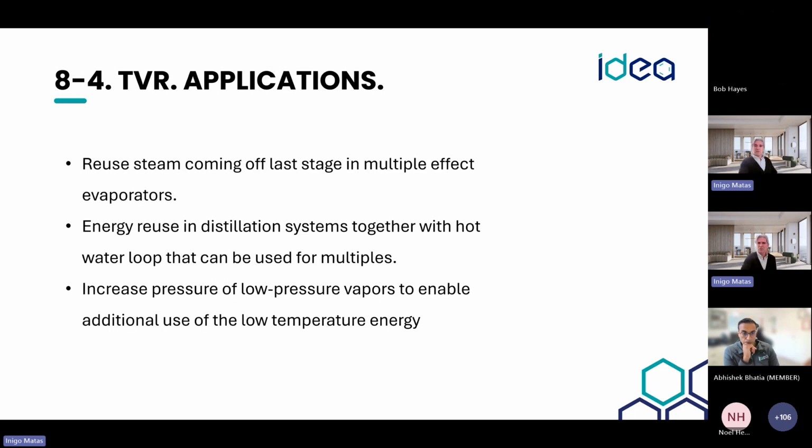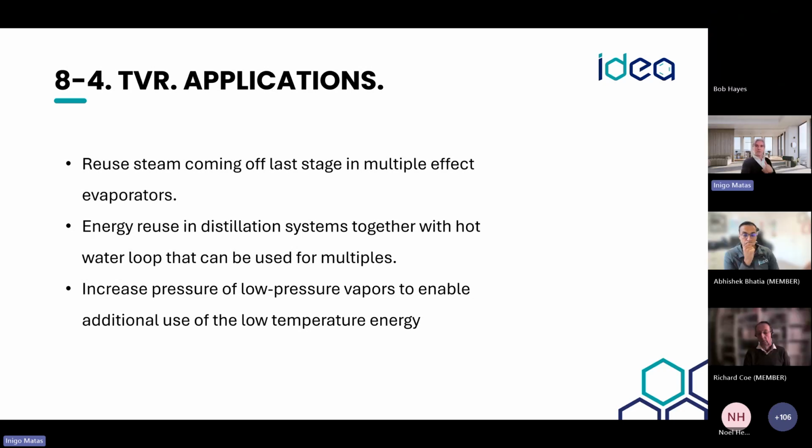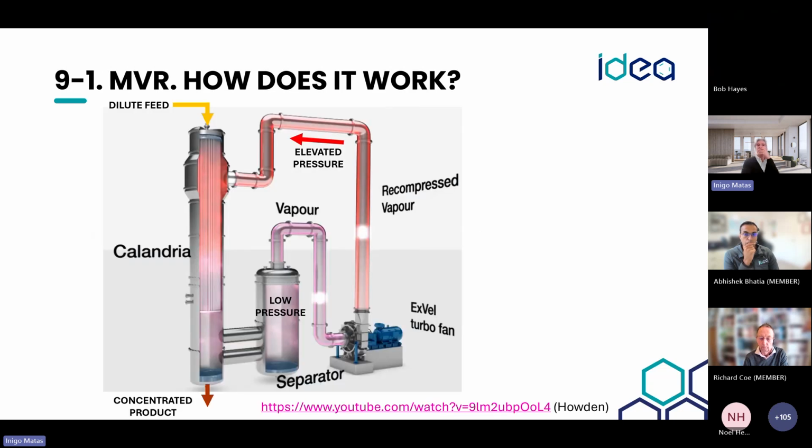Okay, applications. Widely used in evaporators, in the food, chemicals, and wastewater treatment sectors. Also, everywhere where we have a flow of vapors is a potential candidate for a TVR system, and it provides as well a simple and low maintenance way of reducing the steam consumption. Okay, then we go to the next one. I will call this an evolution of the TVR.